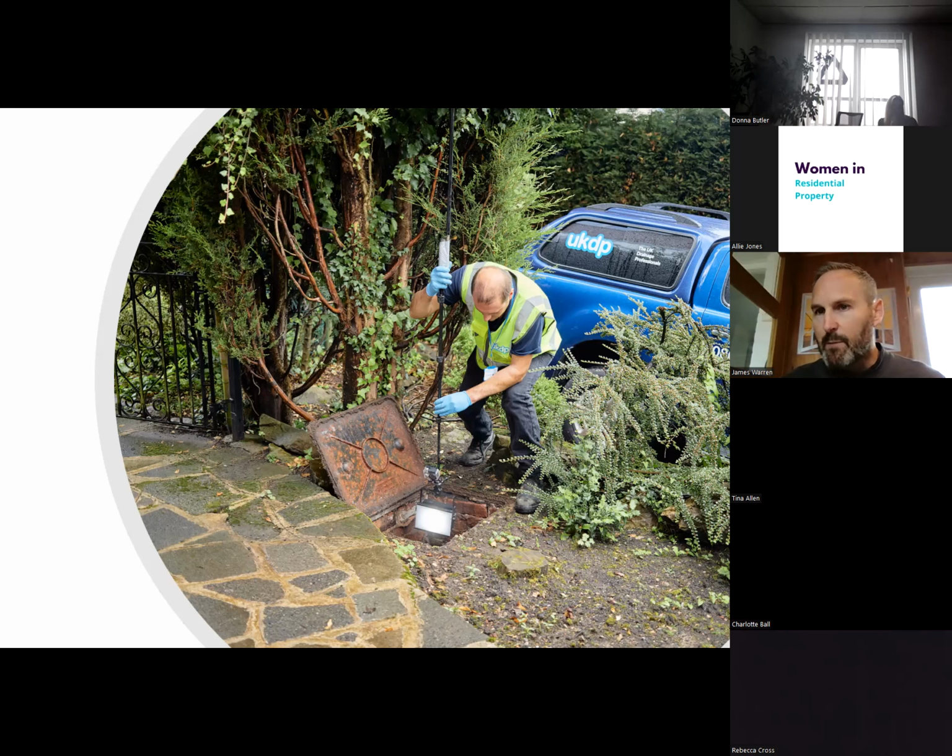If we look inside that tank before it's emptied and the liquid level is below the height of the outlet pipe, that tells us immediately that there must be a structural breach, and therefore water is escaping out of the walls of the tank into the surrounding ground instead of exiting through the correct mechanism of the outlet pipe. So it focuses our engineers' minds on where to look and where to concentrate on the survey.